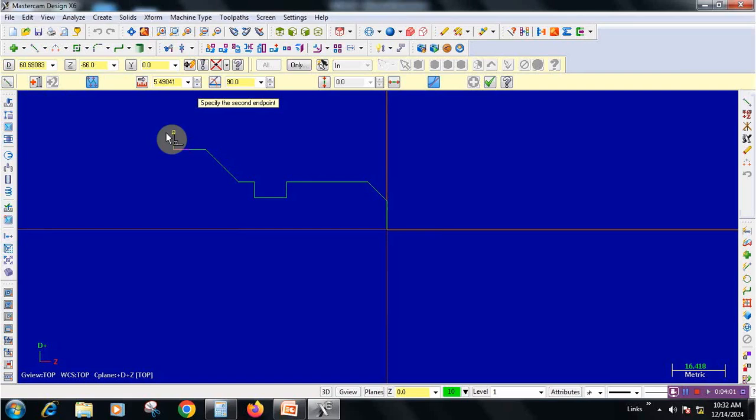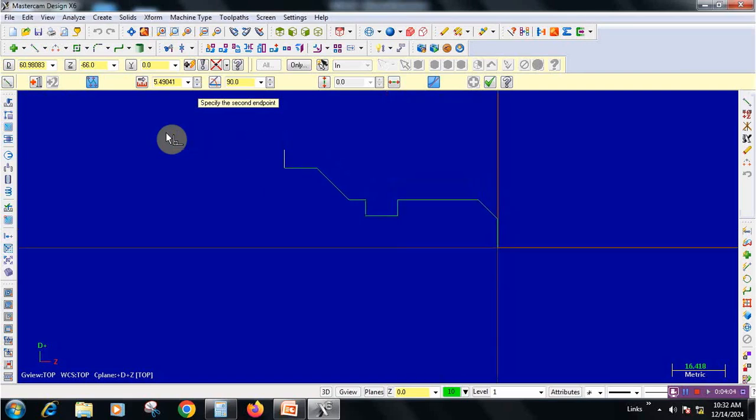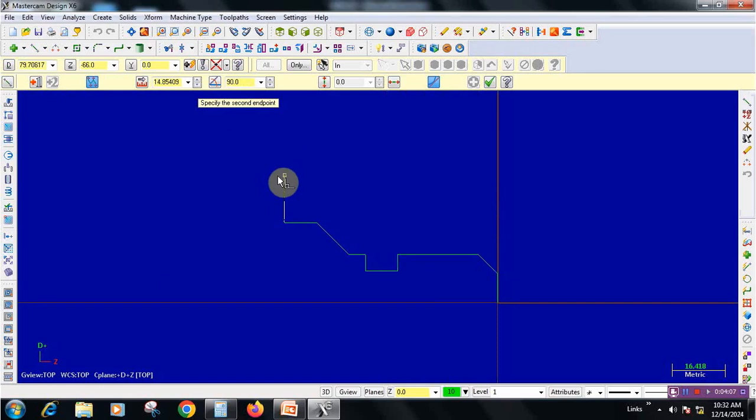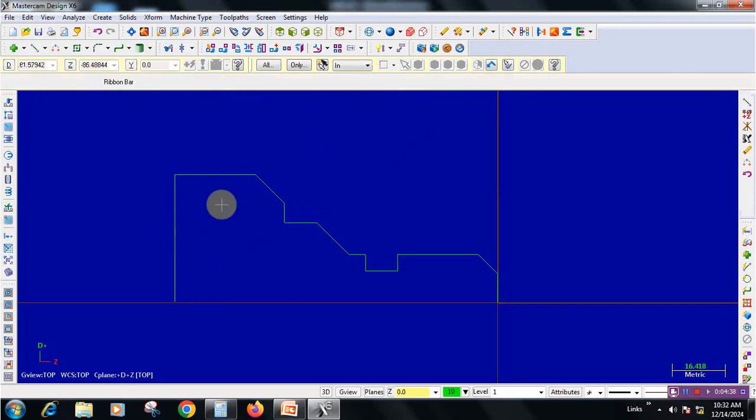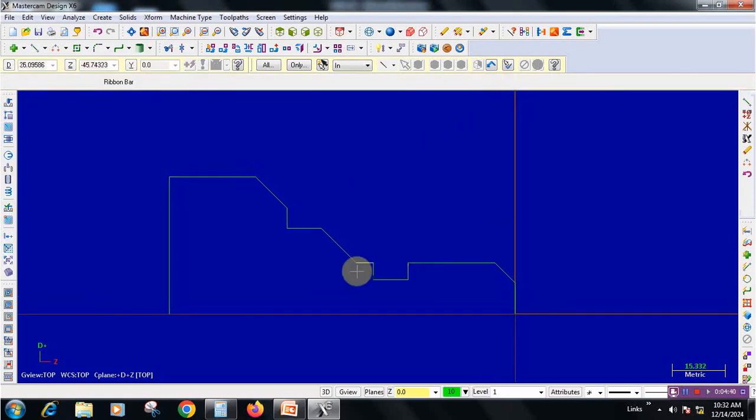We can move the profile anywhere, right, left, top, bottom, anywhere. So here we have one small linear interpolation, that is 62, minus 66 and 80, minus 75, then 80, minus 100. So complete the profile with 0, minus 100 and then give it OK. So almost the profile is over except 2 curvature.